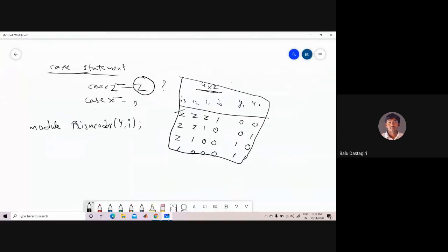Yeah. So now we have to define the inputs and outputs separately. Define input [3:0] I, since it is a 4-bit input. Similarly, output [1:0] Y. When you are defining the output in case of procedural assignment statements, we have to make sure that it is defined as a register. So, reg [1:0] Y. Define the output in terms of registers in the procedural assignment statements.